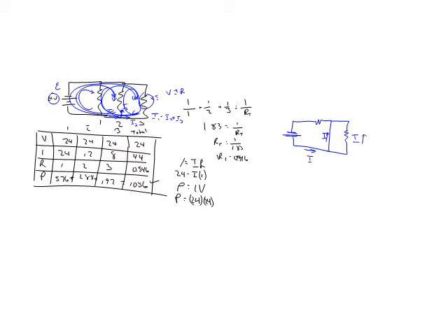So when it splits here, if I'm looking at a loop, and again, it doesn't matter which way you traverse the loop. You can pick any loop you want. There's 3 loops here. We have 1, 2, and then the outside 3. So it doesn't matter which one you want. You just need as many equations as you have missing variables. So we can use a junction rule right here. If this is I1, I2, and I3, our junction rule would be I1 equals I2 plus I3.